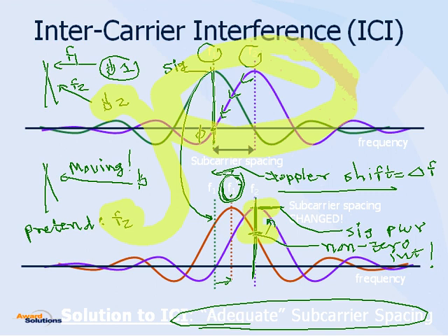Okay, and one, can the users compensate for Doppler? Not really, because this is happening in the uplink. So one user is sending signals, right? Another user is sending signals, and those will be affected in the uplink differently depending on the user speed. So the base station is just taking samples of the incoming signal, and in that case we are not individually processing the signal.